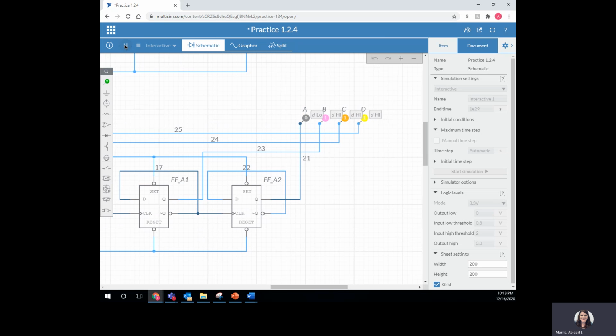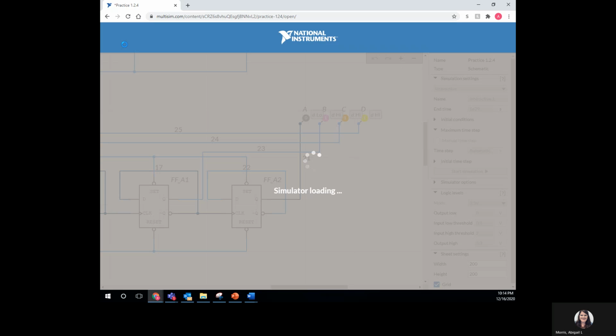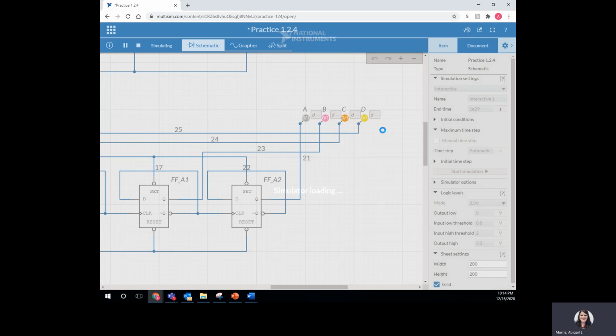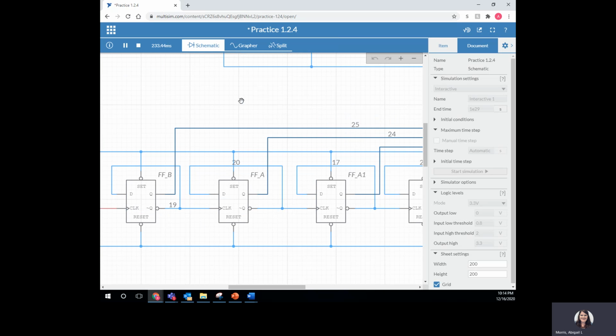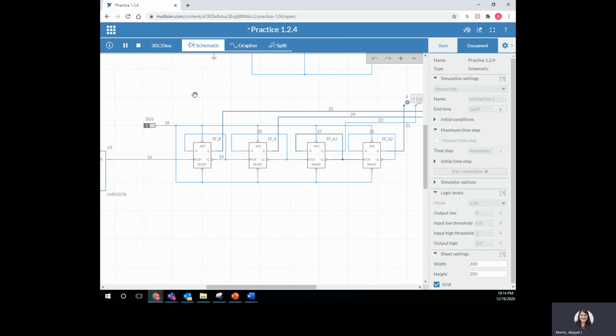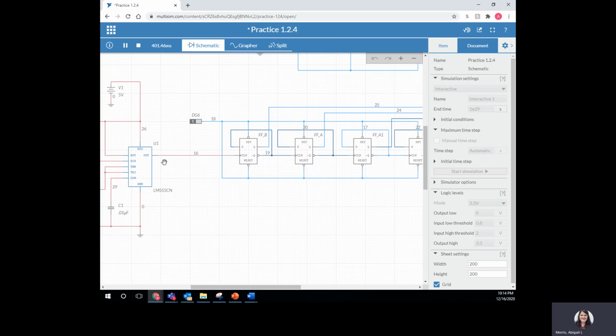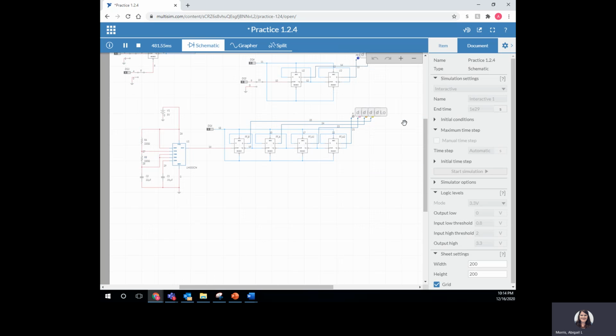It depends on your computer and your internet connection, but basically you want to switch RA, RB, and the capacitor values. You're going to experiment and change these values until you get the perfect pace for you to read the counter. So let's say this was not moving at the pace I wanted.